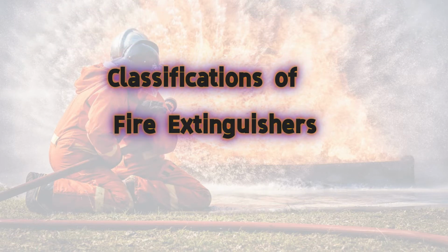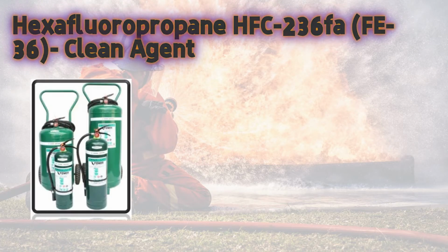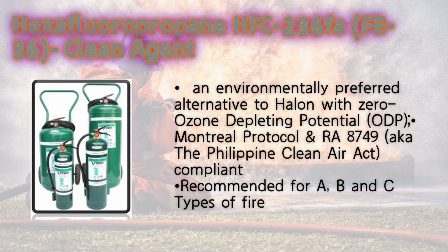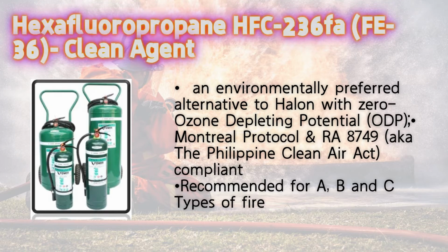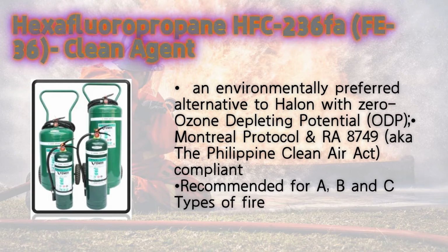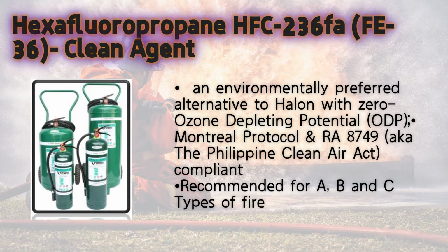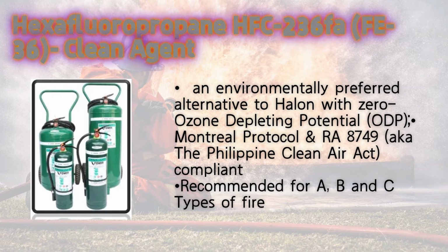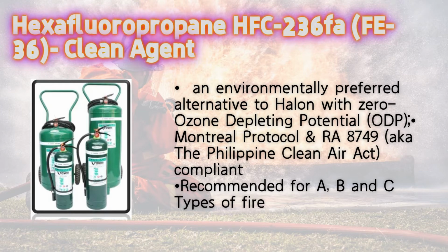Classifications of fire extinguishers. Hexafluoropropane HFC-236fa or FE-36 clean agent. An environmentally preferred alternative to halon with zero ozone depleting potential or ODP, Montreal Protocol and Republic Act 8749, also known as the Philippine Clean Air Act compliant, recommended for A, B and C types of fire.